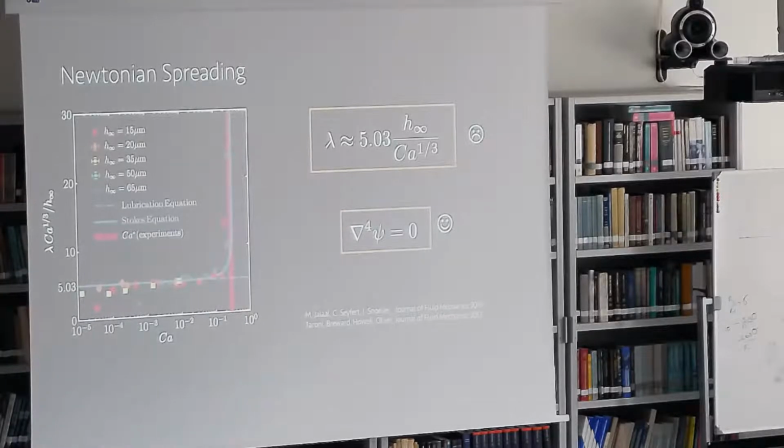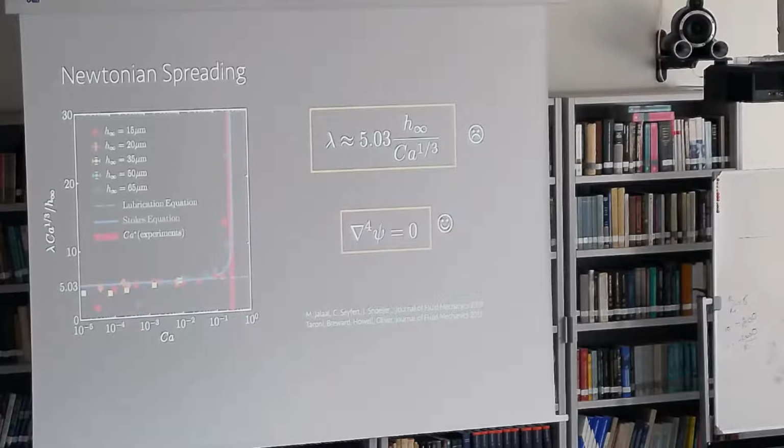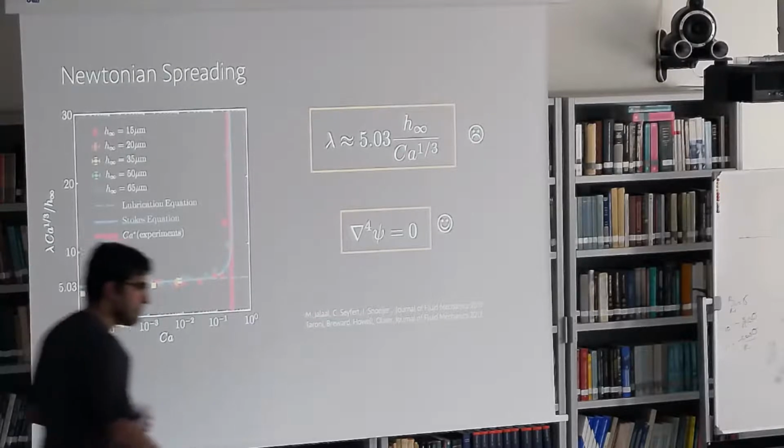Thank you very much. That was very nice. Just a question on, as I'm sure you know, some people argue that pure yield stress fluids don't exist, and there's always elasticity, in particular close to the yield stress limit. And in some cases, people say that this is the dominant effect in real experiments. So could that be a source of discrepancy in your comparison?